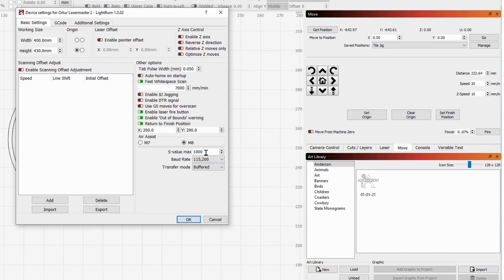What this means in Grbl language is that actually it is a spindle speed for a CNC, so the amount of rotations. But we're not using a CNC, we're using a laser. So it equates to a power instead. 1000 equals 100% in Grbl.